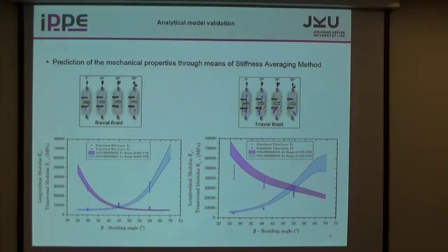When we talk about the ability of the analytical model to predict our experimental results, when we take a look at the biaxial results, everything looks really nice. The areas that you see here are the transversal and longitudinal moduli that the analytical solution predicts, having a fiber volume ratio between 50 and 60%. On the other hand, when we move into triaxial braids, as noted also by our colleagues in the industry, the model tends to overestimate the stiffness obtained experimentally. We are still not sure whether it's our fault from the side of the modeling or it's their fault. Even triaxial specimens have a bit more porosity compared to the biaxial specimens. We are not really sure what happened there exactly.